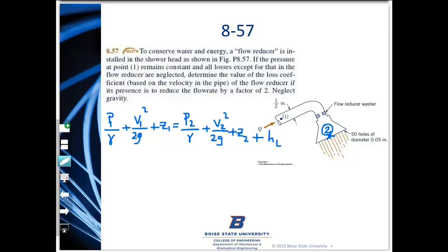Okay, and let me go ahead and write HL is KL V1 square, which is the velocity in the pipe shower head, over 2g.